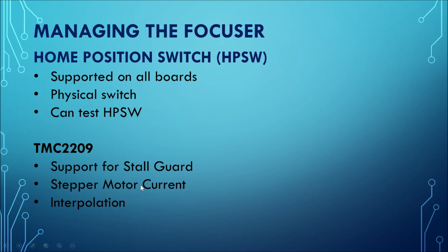There's no fiddling around with some pot trying to get voltage or current right. And the firmware enables interpolation, which means that a single step, let's say one full step, can be broken down into 256 micro steps.